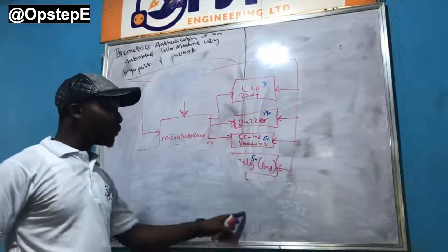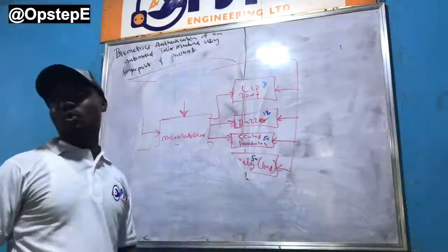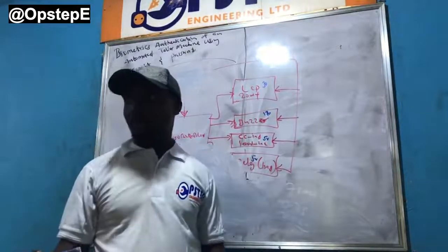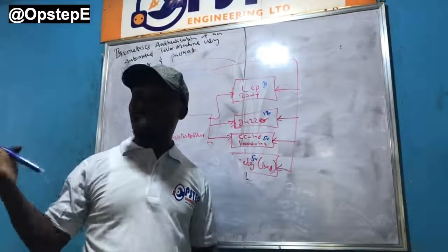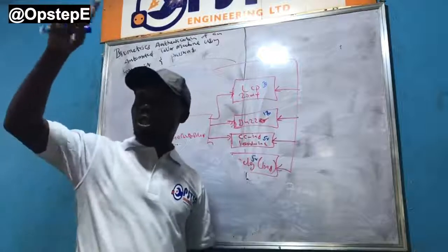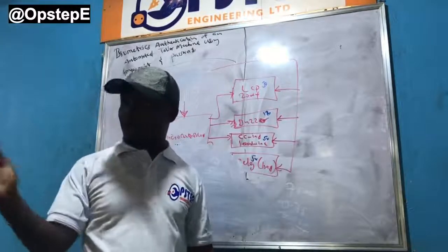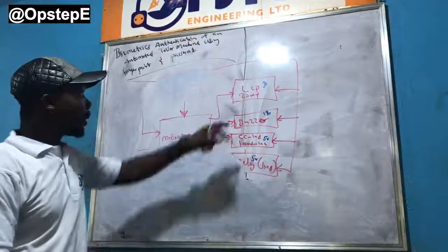Now, on your power supply, don't forget that on the output of that 5 volt you're supposed to have a variable resistor. A 102, a 1K variable resistor, which you use to set your contrast control. We'll discuss all of that before.